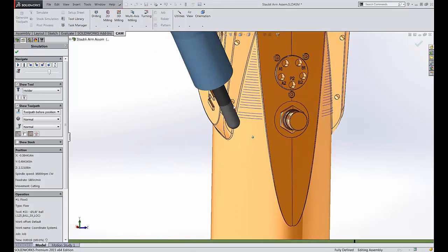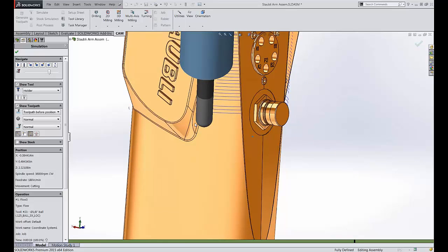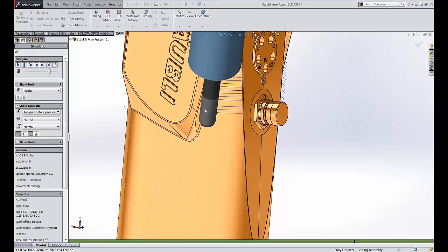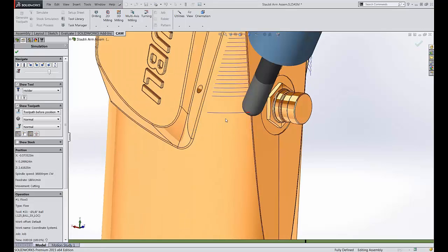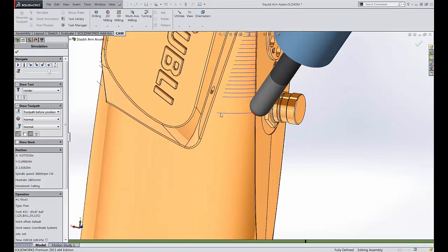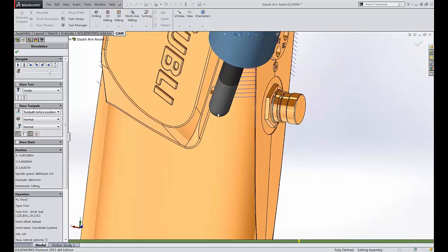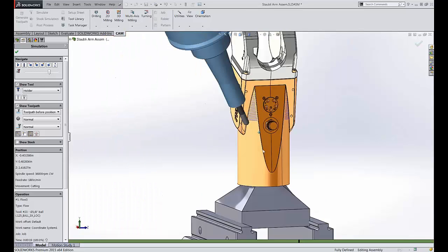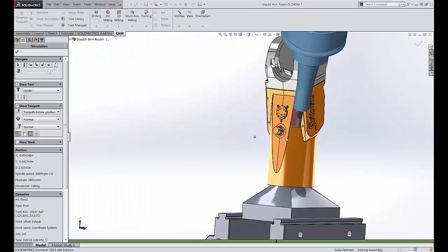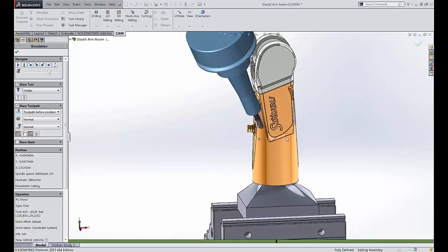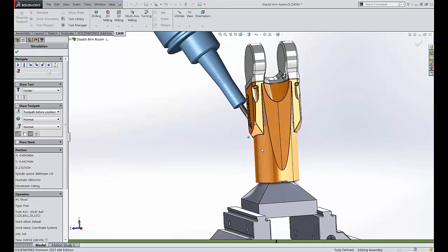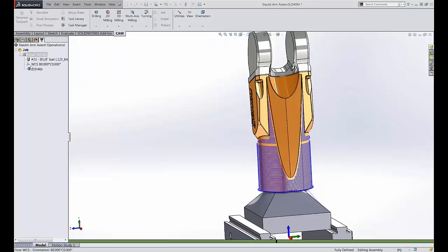So that's a good example of where you don't usually need check surfaces. It probably would be nice to be able to give a little bit more, and I could make an argument for that being implemented, but I don't think that it's an easy thing to just toss in there. But you're getting some nice multi-axis. We're staying away just based on that tilt. It's generating all the way around the surface. So maybe it's done at this point.